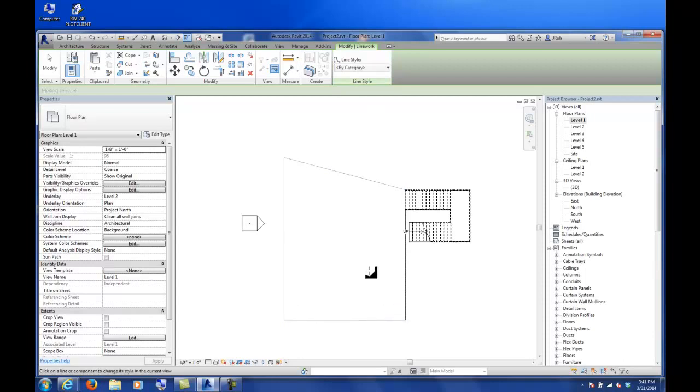No. I'll put underlays under what I'm drawing, but I'm still working in the level that I'm in. Right. So I've got the level 2 underlay, but I'm in level 1. So I'm looking at the floor above. That's what this gray dashed line is. That's the floor slab that's above. And it doesn't matter what line I use. If I'm using the line work, I could use hidden lines if I wanted to. And I'm selecting each of those elements, and it's tied to that floor slab. And if I turn off this underlay now, those lines still stay in level 1 floor slab.